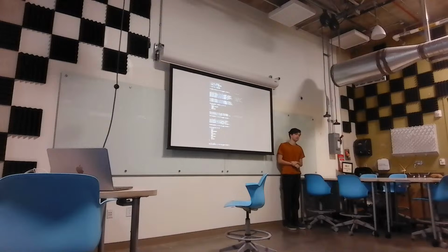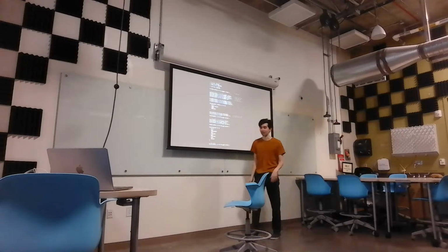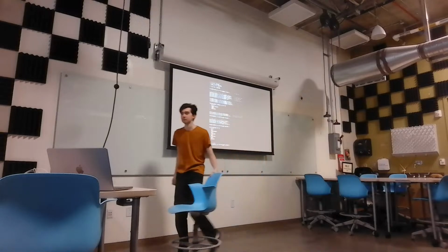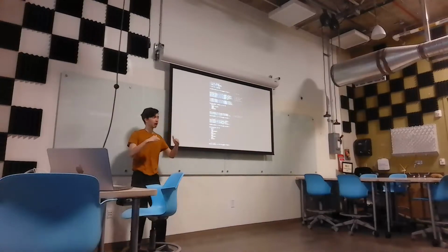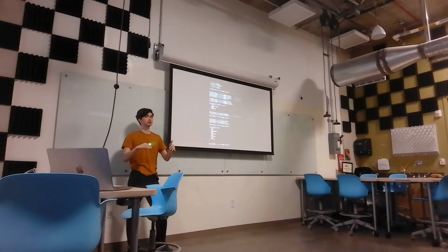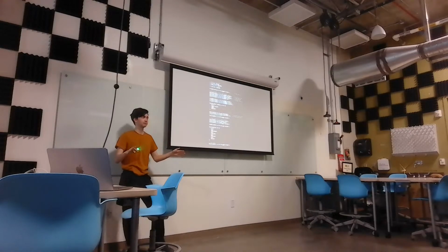Done for, because it's shorting the battery. Percent battery through the top FET, through the bottom FET, ground. There was nothing there. We just connected the battery to ground. That's not good. We don't want that, of course. So we need the PWM signals to guarantee to be opposite of each other or both zero. Does that make sense to everyone?